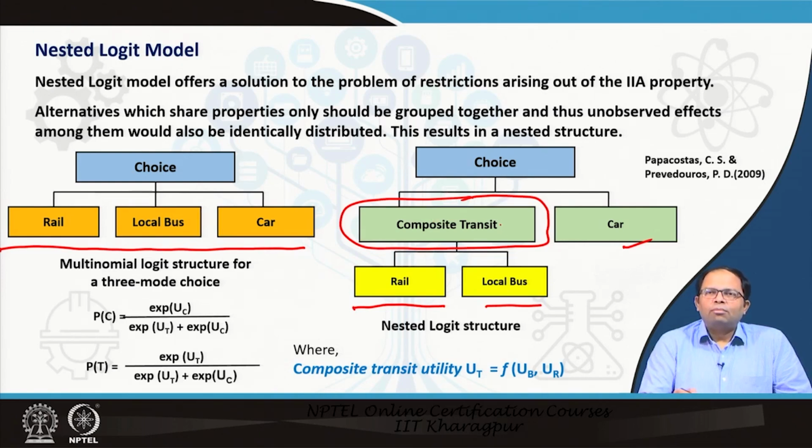So, the same model that we were doing during RP and SP joint estimation, we were using a nest, but it was a dummy nest. That means it was a composite nest including only one alternative. So, we were fooling the estimator by saying that it is a nest. So, there has to be a theta for that, a scale parameter for that, but at the same time there is only one alternative in that nest. This is the explanation for why we are using a nested logit structure to estimate a joint RP-SP model. But in any way, over here we create this nest.